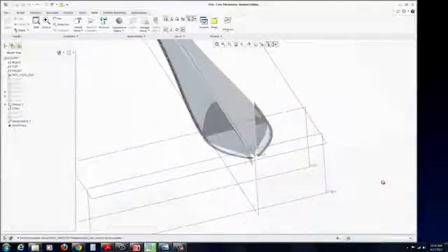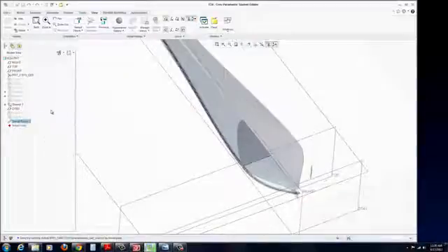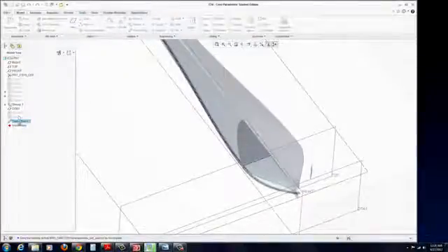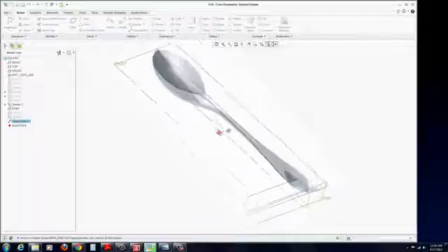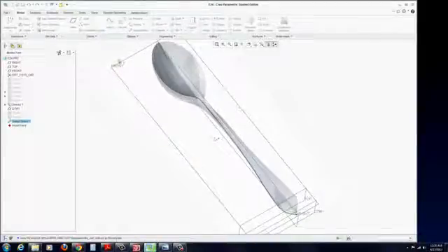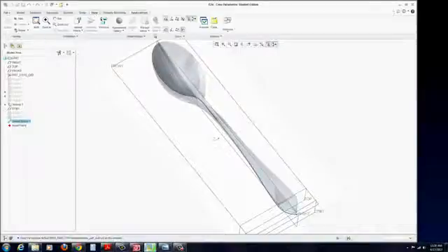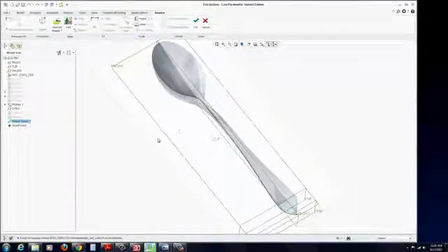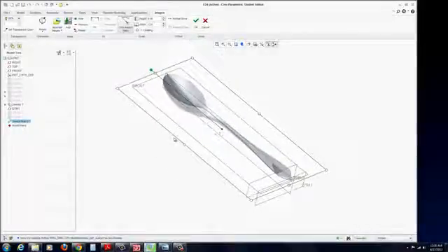Okay, that one I seem to be having a few problems, but essentially, as you can see here, this is when it is completed. The swept blend should come out like you see there. Now to get rid of the images that you have inside there, it's just a matter of going back to view, and then if you go to model display images, you can now click on them and then right click. You should be able to actually delete them.